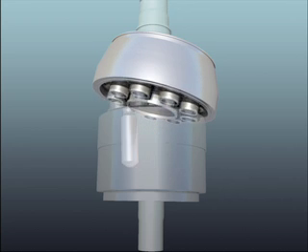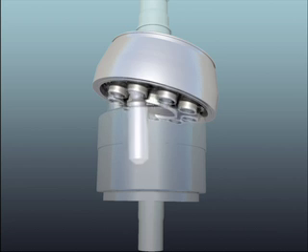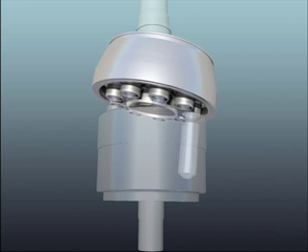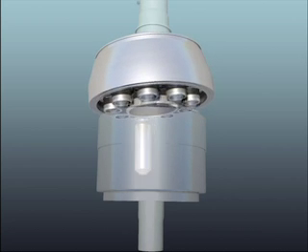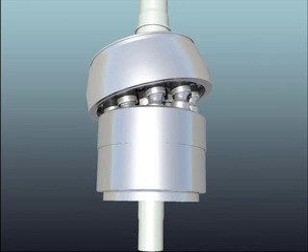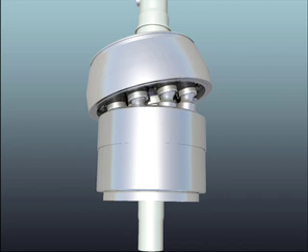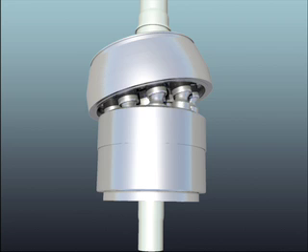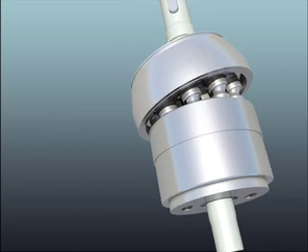If the rotation direction of the pump shaft is reversed with unchanged cam angle, then the pistons will move in the opposite directions, which will reverse their pumping action. This will lead to the inlet and discharge ports changing place, which means that the flow direction of the pump will be reversed. Some pumps have the ability to move the swash plate over the center position. If this is done at the same time as the pump shaft rotation is reversed, then the piston movement and thereby the flow direction of the pump will remain in the original direction.